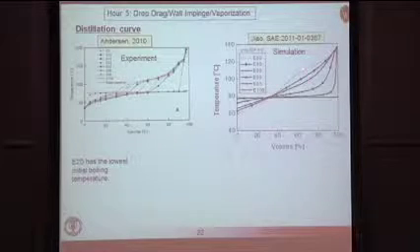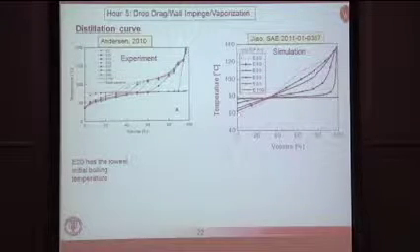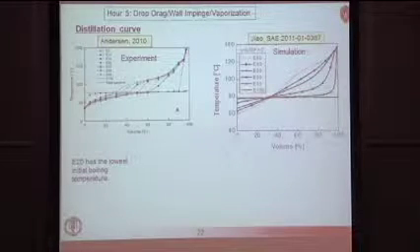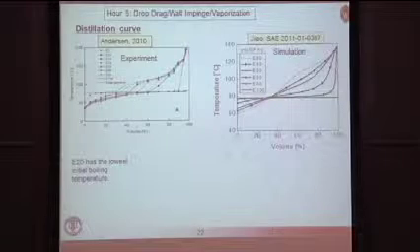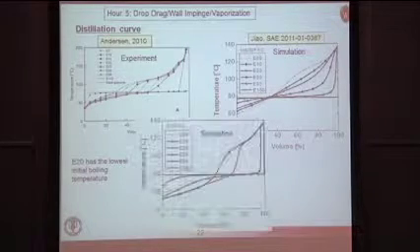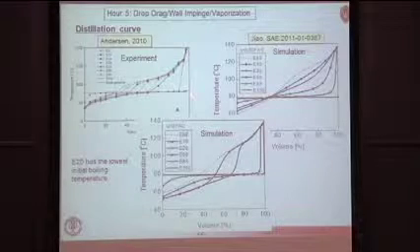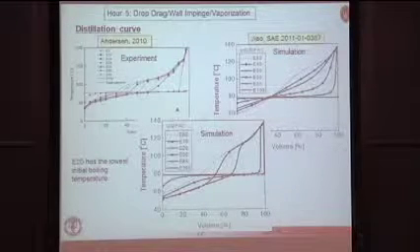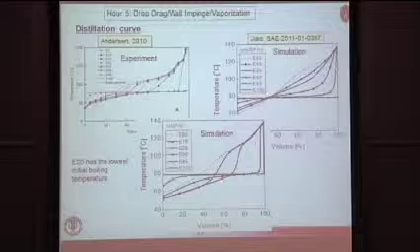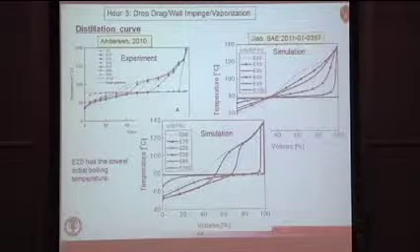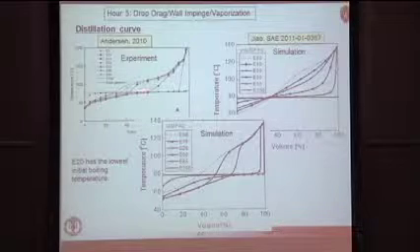If, on the other hand, we look at the simulation for E20, we just don't see that. We just see a much more gradual rise in the distillation temperature. That's without using this interaction model. But if you use the UNIFAC model, you see something that looks a lot more like the experiment. You see basically at around 60% suddenly an increase in the boiling temperature, consistent with the experimental data.